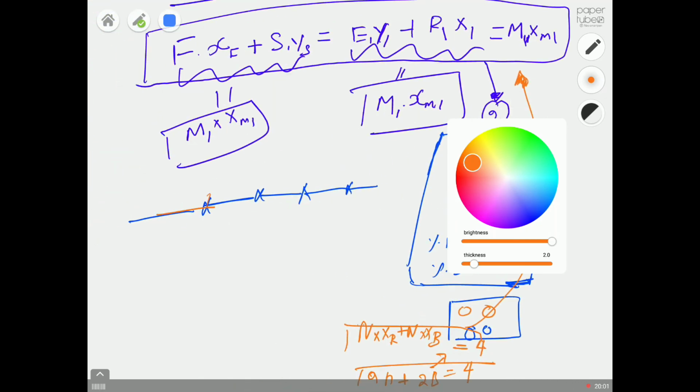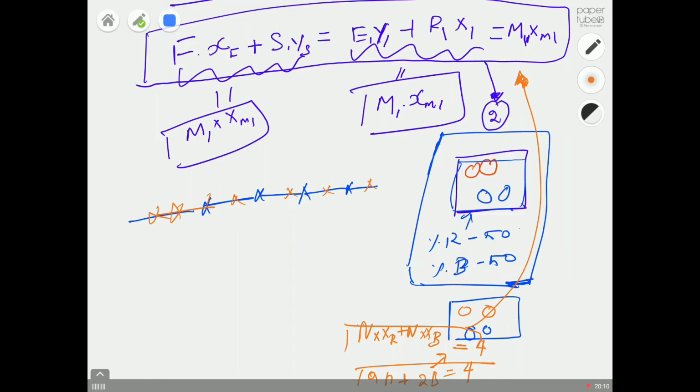Yeah, so don't get scared of this word mass balance. Mass balance is a very easy concept, but it is easy only if you have all the information that you need. You should know the mass that goes in, and you should know the fraction of each component in each of those streams that go into some unit. If you know that, then it's easy to perform your mass balance calculations. Yeah? I'm going a bit slow because I want the pharmaceutical chemistry students to know what a mass balance is about. It would be unfair if I don't explain this to you.